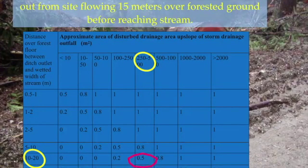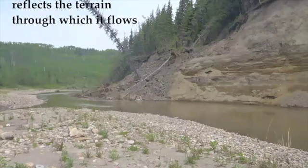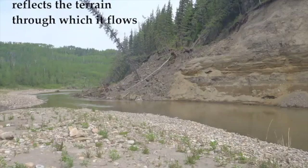It is really important what kind of terrain you are on when considering sediment generating potential. In this case, we are looking at a very fine textured material in the Peace River area. Some of the fine materials in the Powell River area are covered in a coarse sediment, and then underneath this coarse sediment, there are highly erosive lacustrines. Along this creek, there is a large deposit of lacustrines buried under a layer of coarse sediment. If you expose these fines under the coarse sediment, you are open to very serious water quality problems.